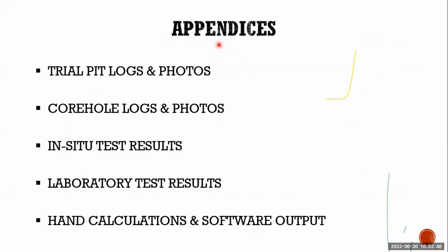The software we use is HoleBASE, a Bentley product. In the appendices, we include the trial pit photos and logs with descriptions of the strata, core hole logs and photos, and in-situ test results, either SPTs, pressuremeter, DMT, or CPT. We also include laboratory test results and certificates, the hand calculations, and any software output.